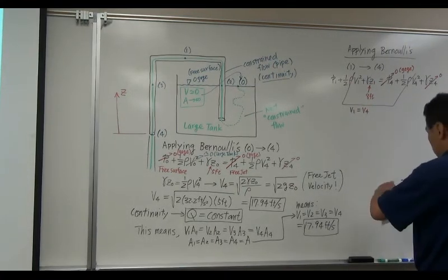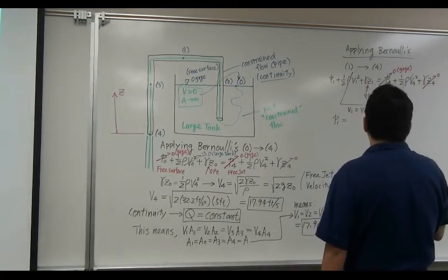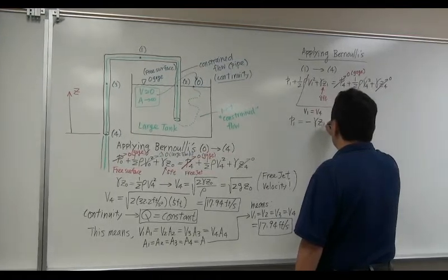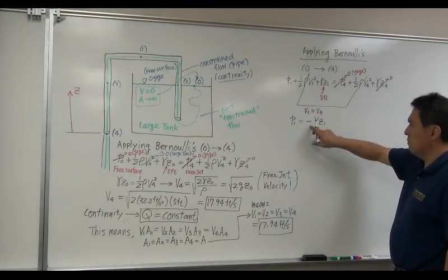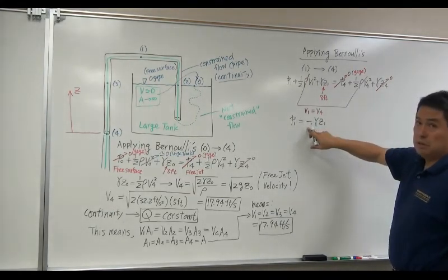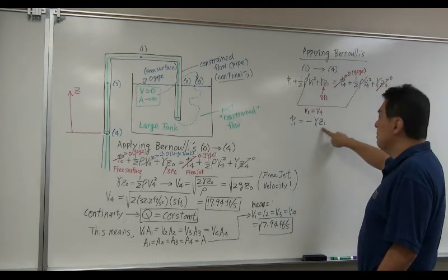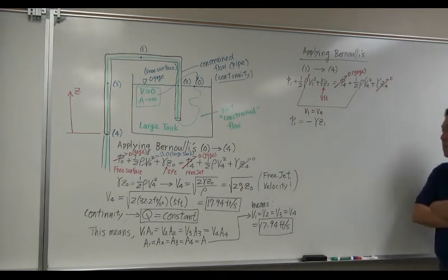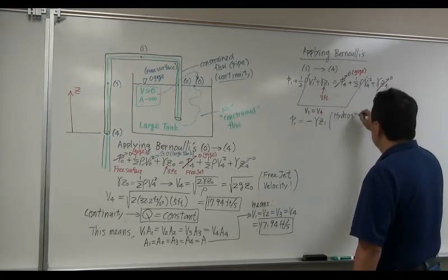So that leaves you P1. P1 is equal to minus gamma Z1. So pressure P1 seems to be lower pressure, in other words, minus pressure. Minus pressure, so this is less than atmospheric. So a negative gauge value, that's what you expect to have. Gamma times, what's this? Depth or height? What kind of equation is this? Wait a minute. I stop and think, hey, I've seen this equation before. What is this equation? This is purely hydrostatic pressure variation, right?